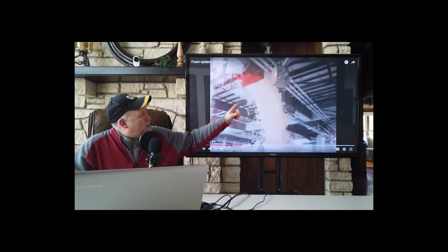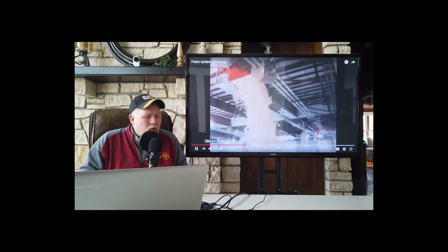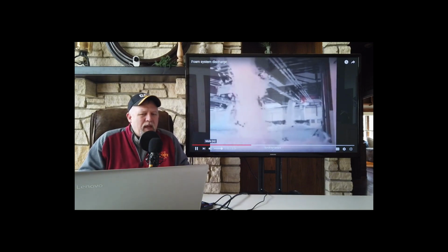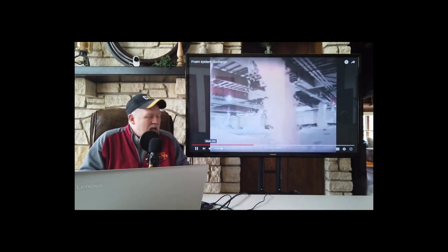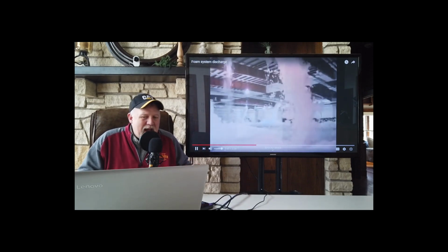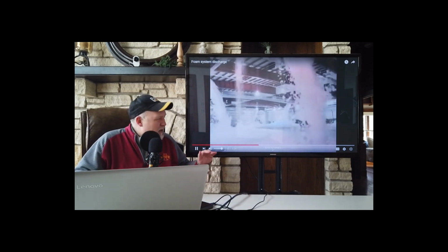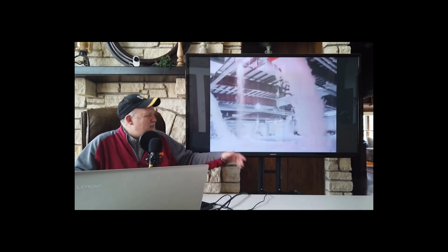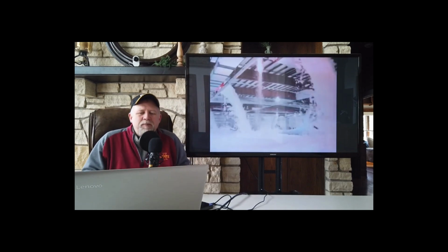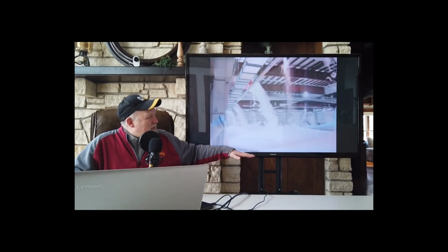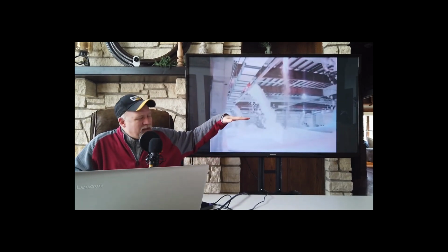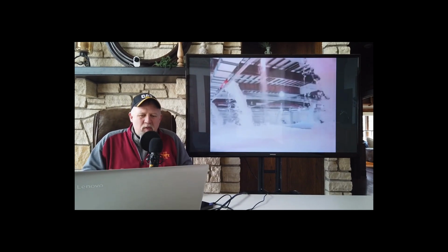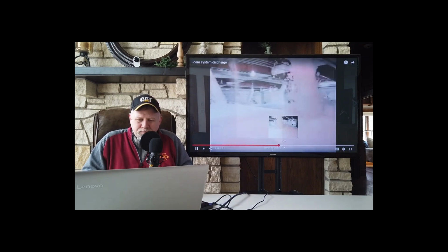So, I mean, look at the sheer volume. It's only got a few minutes. They're doing a test, and they're timing it to see how fast it can fill up this hangar. And for the test, you don't fill the entire hangar. You do a controlled fill, like you figure out, okay, 3 feet or 4 feet, time it and see how long it takes to fill it to that level. So it fills the entire thing up to the level necessary for whatever aircraft is in there, and then it extinguishes the fire this way.